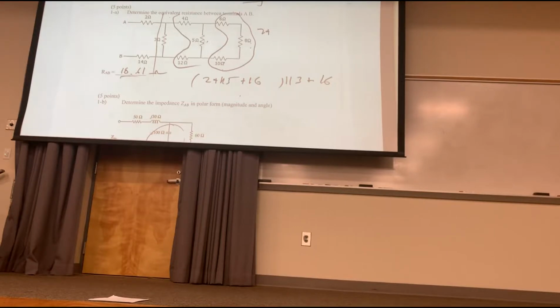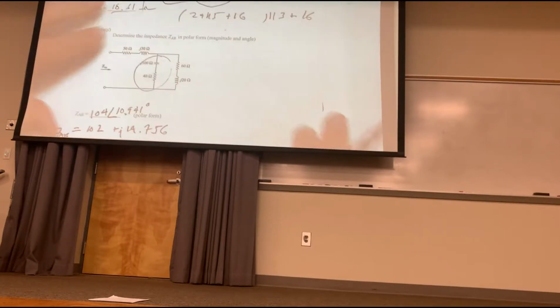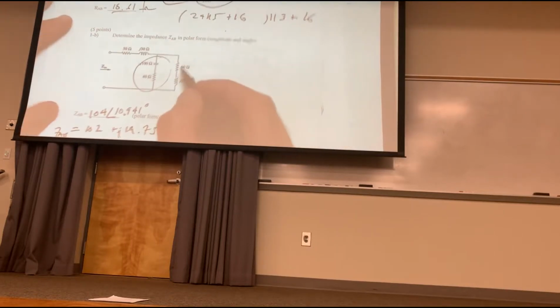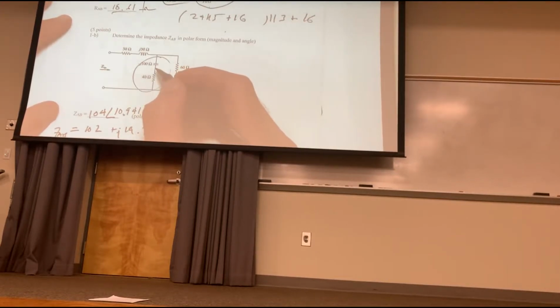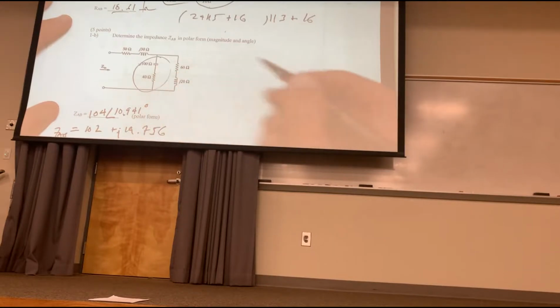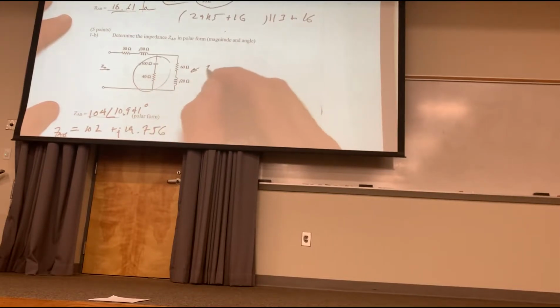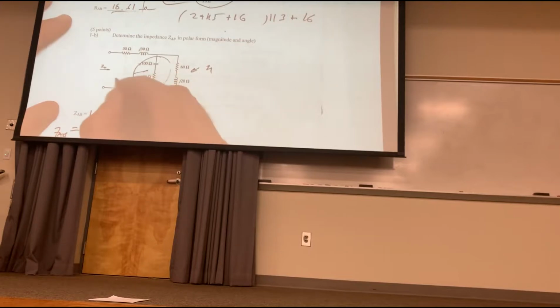They were straightforward. They're just checking boxes. You know how to add resistors in parallel and series. That's the first one. Now you know the next part is how to add complex numbers, series and parallel. And this is just using your calculators. Here for this one, I have two impedances in parallel. I have 60 plus J20, and I have 40 minus J100. You all follow me? You can label this impedance as simply Z1, and this impedance as Z2.